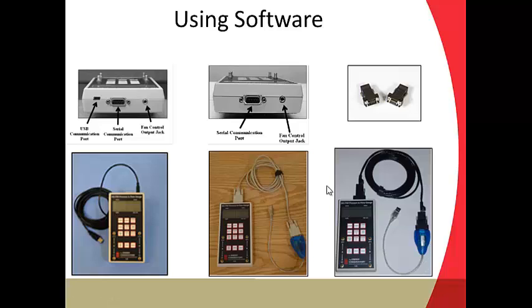We do have serial to Cat5 adapters that we sell, and those can be used with Cat5 cable, regular computer cable, to run as long a length as you want, and that cable is readily available. We do recommend using stranded rather than single conductor cable if you're going to be using it multiple times. The single conductor is what's sold at most big box stores, and that works fine if you're just running it through an attic or through a house and you're not going to be rolling it up again.